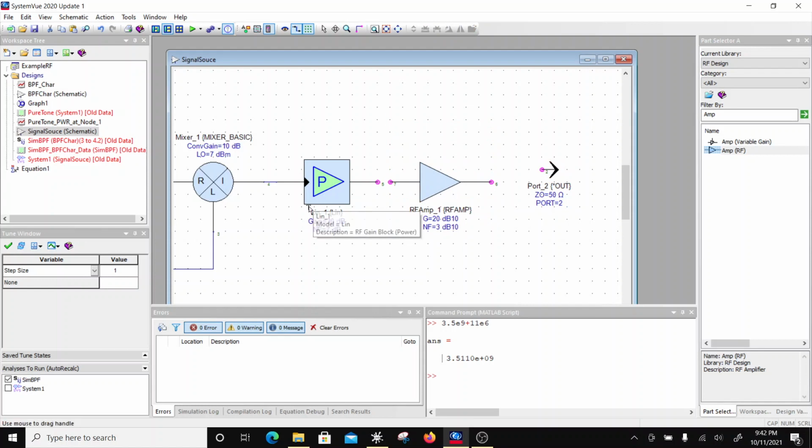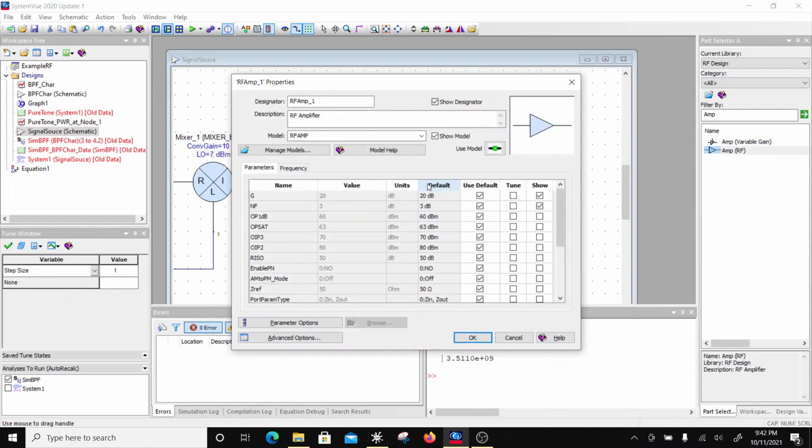Okay, so this looks like a linear, so it says LIN means it's a linear gain, right? And this can be a non-linear block, which is a PA. So this is like a driver and this is like a power amplifier. And let's say the gain is around 30, so the overall gain is 60.